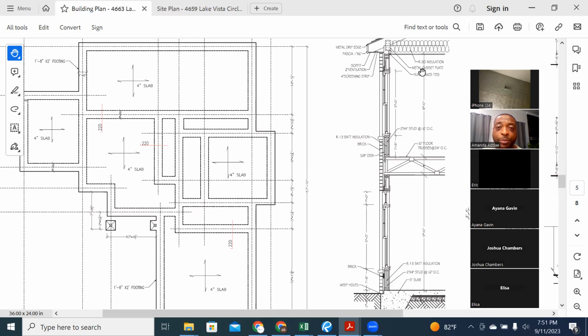If your slab is prepared appropriately, that's all that you need. So at this point, if you've passed that, the county has done their job. Now, when you pour concrete over it, there's nothing else to test. So long as you pour 4 inches thick, you're good to go. But someone like myself could say, I want an 8-inch pad, an 8-inch concrete for my foundation. I have every right to pour more than I need. But the minimum I need, so long as I pour the 4 inches, I'm good to go.